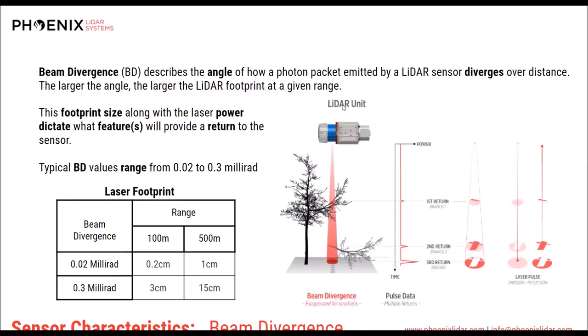I would say that given the same range, you'll see them perform nearly identically. But the ability for the LR to go to a higher range, while that is an ability to detect targets, you will get a worse precision from those larger ranges. So you can see that idea from 2 different sides of the same coin. Okay, great. I think they have a 5 millimeter difference in spec in terms of accuracy and precision. That's often hard to make out, right, in post-process data, especially if you shoot from far away.